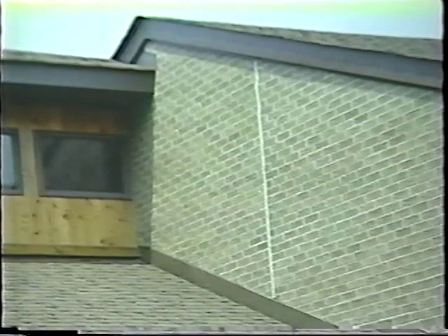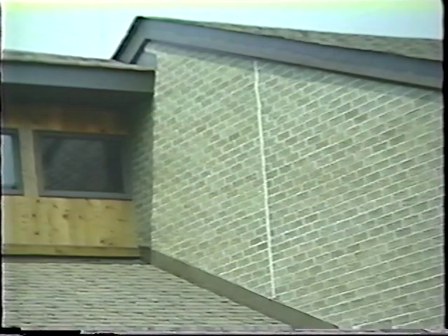In all cases, through-wall flashing and counter-flashing are very important to reduce water penetration. The brick supported on the wood must be separated from brickwork supported on the foundation by a vertical expansion joint. Without exception, through-wall flashing and counter-flashing are very important to reduce water penetration. Brickwork must be properly supported to avoid problems or failures. A strong, rigid support is necessary to achieve adequate bearing.